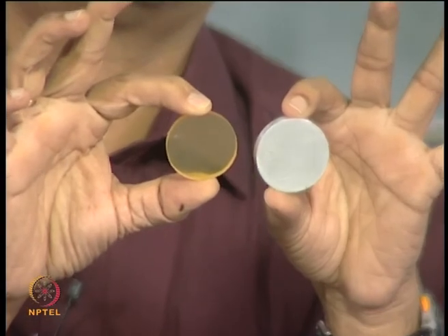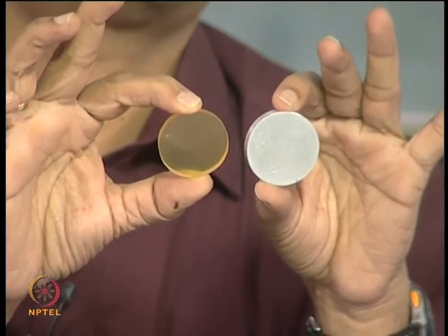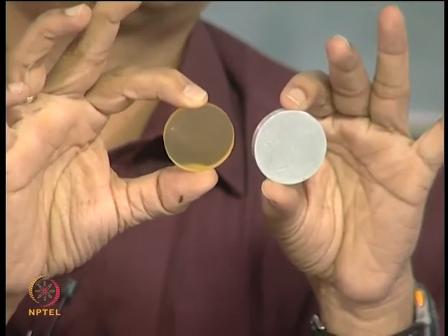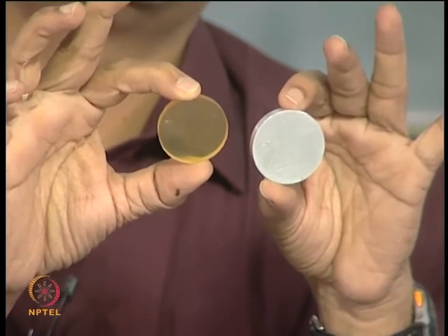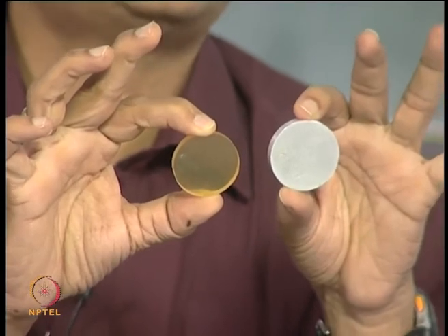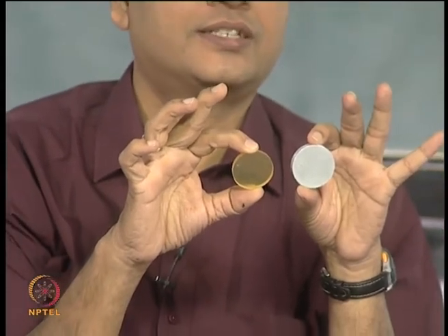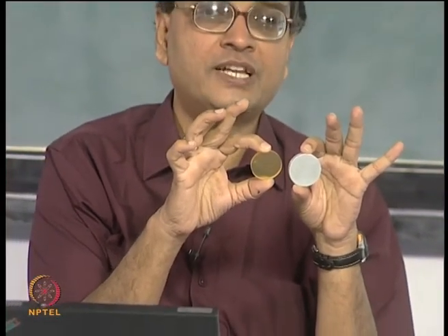I said what is the nature of the stresses developed, because polyurethane is a plastic which has a low Young's modulus, you can visually see the deformation. Aluminum is so strong, it has about 70 GPa and this is about 0.3 GPa, it is a very small value. So, the deformation is definitely different, there is no two opinion about that. The question I asked was, for the same load and for the same size, how would the stresses be? It is a plane problem.